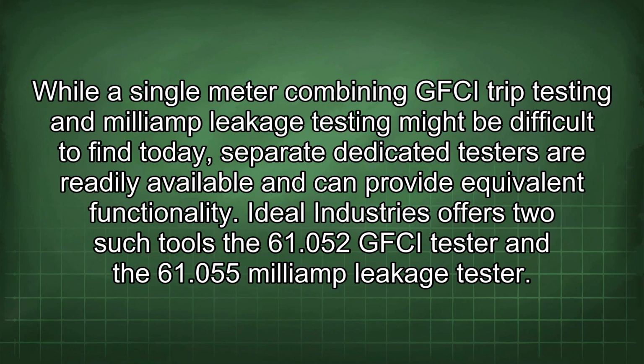While a single meter combining GFCI trip testing and milliamp leakage testing might be difficult to find today, separate dedicated testers are readily available and can provide equivalent functionality. Ideal Industries offers two such tools, the 61.52 GFCI tester and the 61.55 milliamp leakage tester.